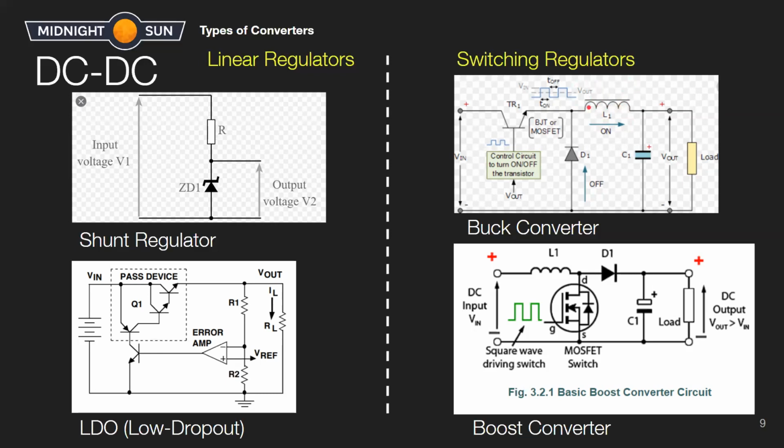So what happens in the current is that the current goes still through the load because the inductor is providing it, and then it goes through our flyback diode. So this diode continues the loop as our input source is now disconnected. And then our capacitor is like the inductor's assistant.